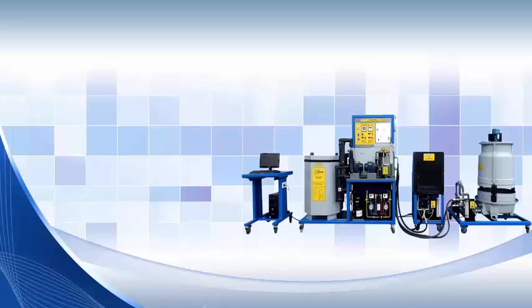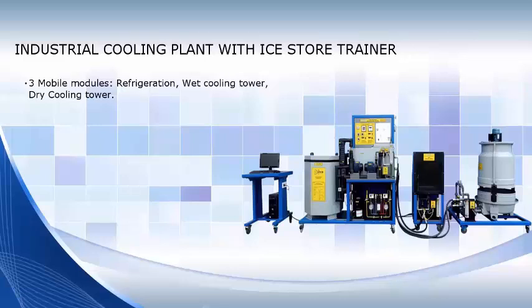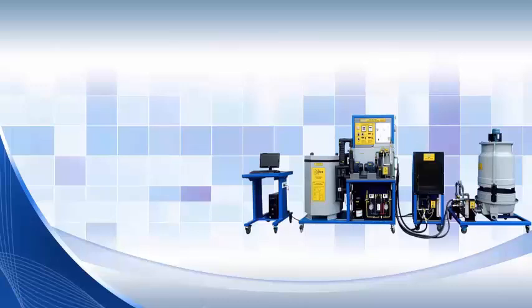This photo shows Labtech's industrial cooling plant with ice store trainer. This trainer is comprised of 3 mobile modules joined together by hoses. The basic module contains the usual refrigeration components along with the brine circuit and intermediate tank. The other 2 modules consist of a wet cooling tower unit and a dry cooling tower unit. The system is equipped with valves to configure various operating modes such as charging, discharging, or bypass. The heat transport is accomplished by using 3 different circuits: refrigerant, water, or glycol-water mixture.